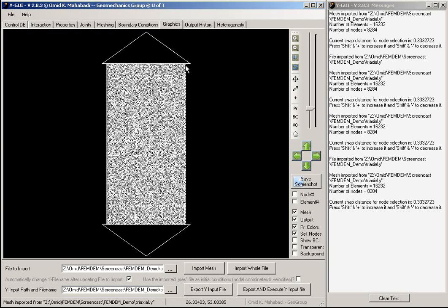So since my model is fairly small, I decided not to use SI units, because if I use SI, then the width of my specimen will be 0.05 meters, and in each time step the amount of strain or deformation that you calculate will be really small, and I'm afraid that I will have rounding errors.